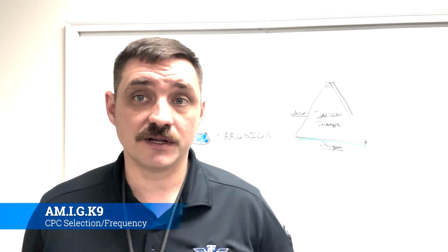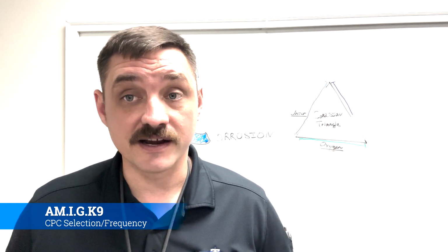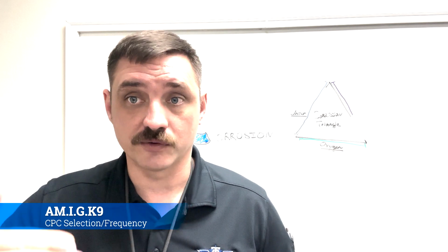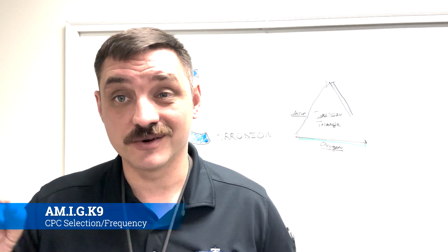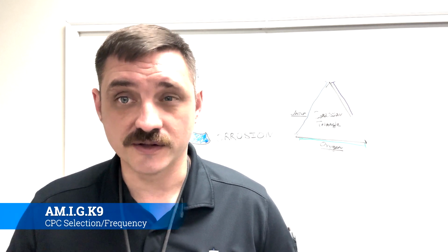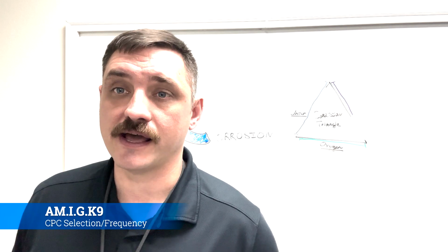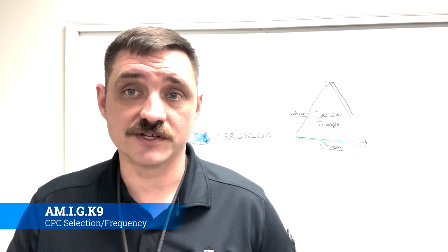Now AC 43-4 will actually tell us how often an aircraft is supposed to be inspected for corrosion. And in theory, if you're inspecting for corrosion on a regular interval, then you should also be inspecting the anti-corrosion coatings that are on these parts, and if there's corrosion there, removing it. So that gives you an idea of where you'd be at. But ultimately, your aircraft maintenance manual should have all this incorporated into it. But if not, we're going to read through them.